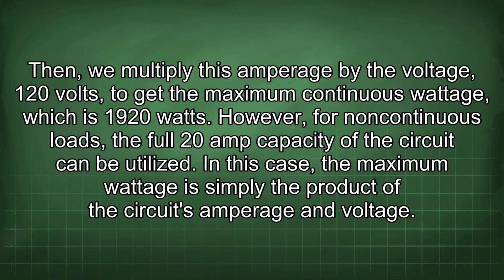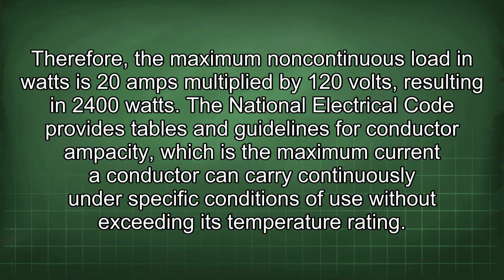However, for non-continuous loads, the full 20 amp capacity of the circuit can be utilized. In this case, the maximum wattage is simply the product of the circuit's amperage and voltage. Therefore, the maximum non-continuous load in watts is 20 amps multiplied by 120 volts, resulting in 2400 watts.